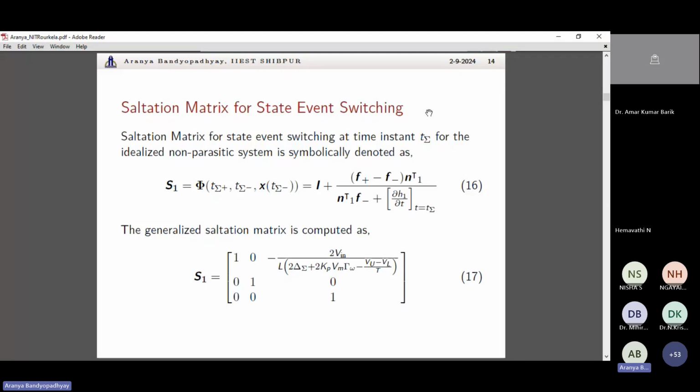There is no explicit formula for it, but from our experience, we have seen that the average method, or the type of Bode plots that you deal with, can predict instability or dynamics of a system only up to 1/10 of the switching frequency or something like that. But any instability that manifests at a higher frequency range, it won't be able to predict.